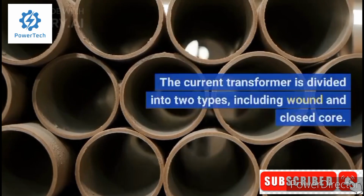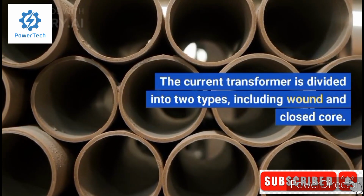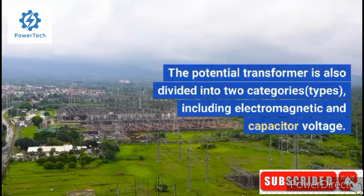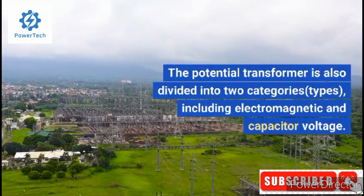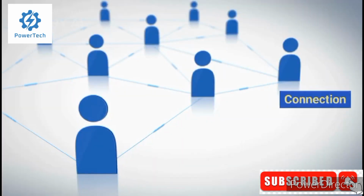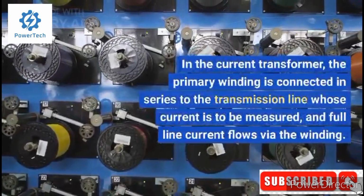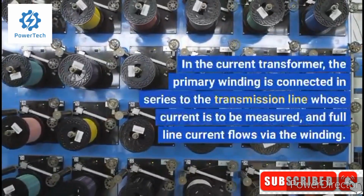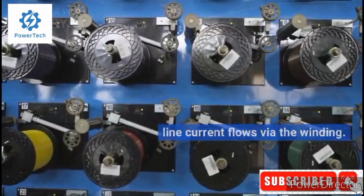Types. The current transformer is divided into two types, including wound and closed core. The potential transformer is also divided into two categories, including electromagnetic and capacitor voltage. Connection. In the current transformer, the primary winding is connected in series to the transmission line whose current is to be measured, and full line current flows via the winding.